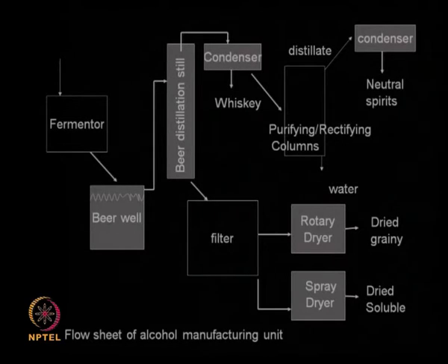Azeotropic distillation involves adding a third component, an entrainer, so that the azeotrope is broken, or sometimes you add an adsorbent so that the azeotrope is broken. So if you want 100% ethanol, you need to resort to breaking this azeotrope, that is on the right hand side here actually.